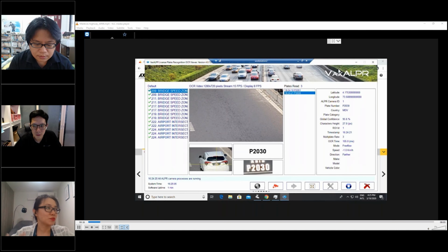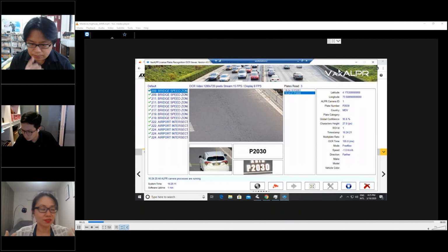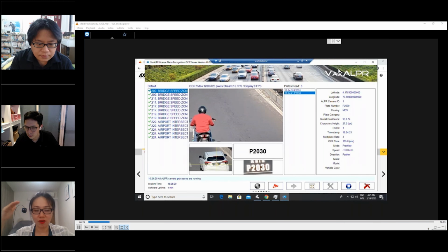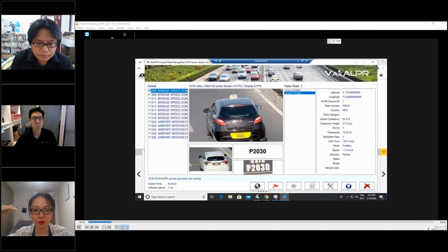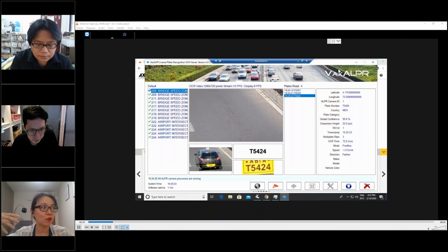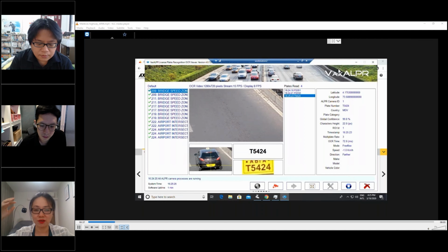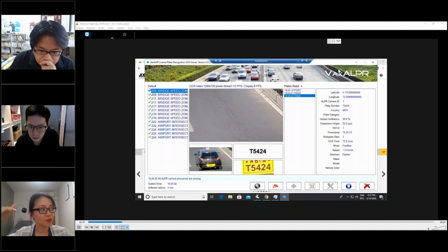The reason was because Maldives is an island, so there's a very strong so-called seaside wind. On top of that, the lamppost itself is 7 meters high. But the problem is that the lamppost was not designed for that kind of application, so it is very thin. After they install the horizontal extension bracket, plus the camera's weight because of the height, it keeps on shaking.